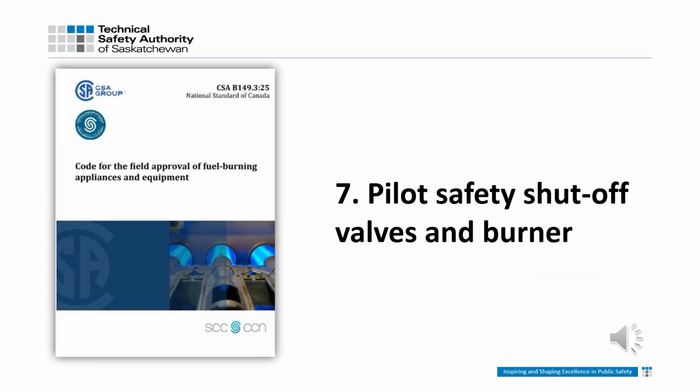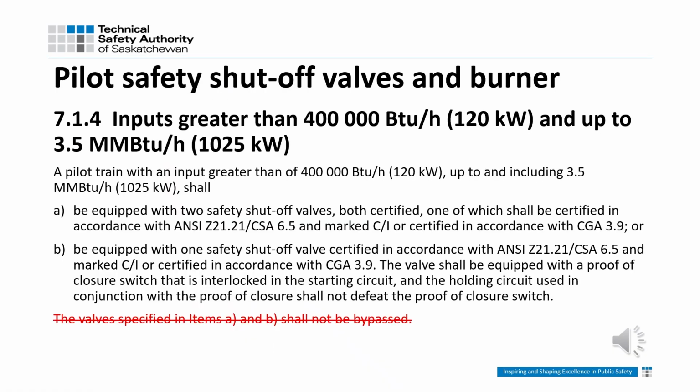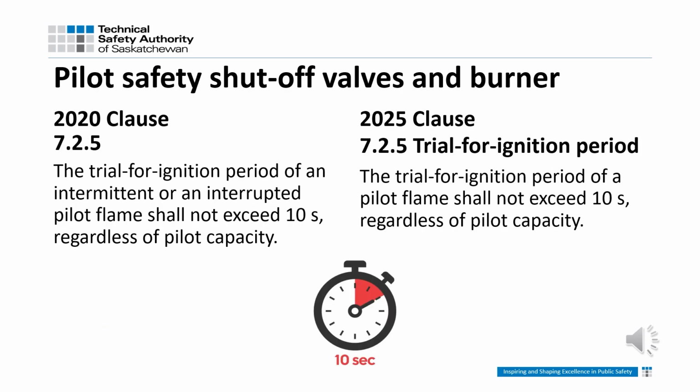Section 7. Pilot safety shutoff valves and burners. 7.1.4 was changed. The sentence in red has been removed as it is redundant because valves are required, so the additional statement that they cannot be bypassed is unnecessary. 7.2.5. Trial for ignition period. This clause takes out intermittent and interrupted pilot flame and just uses the term pilot flame in the 2025 edition. The requirement for 10 seconds has stayed the same.